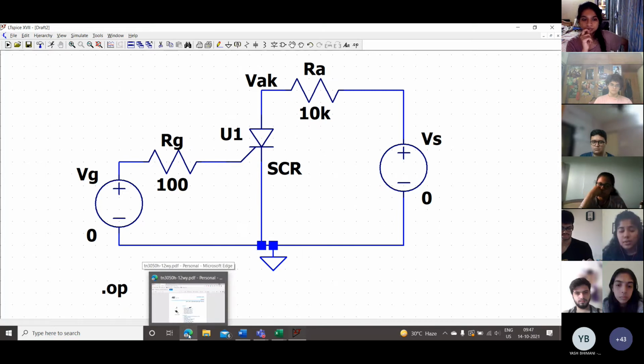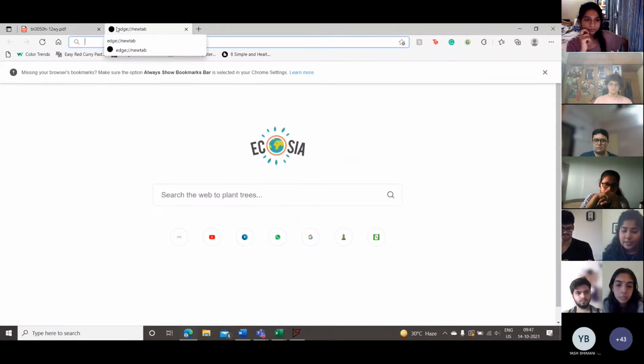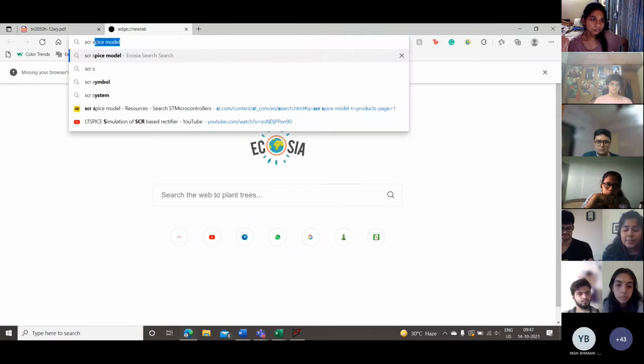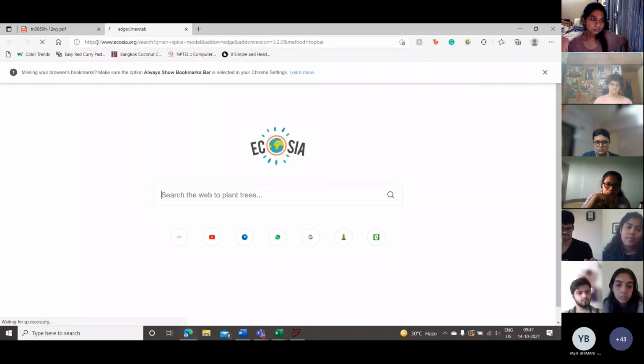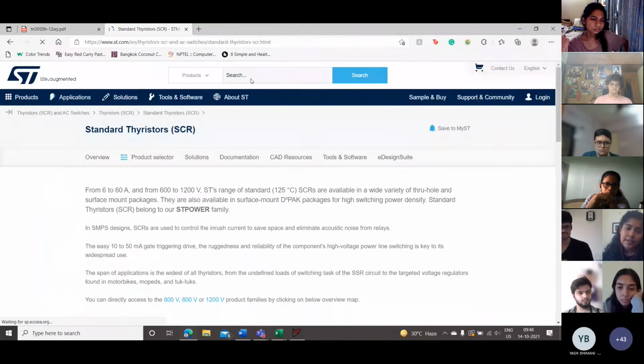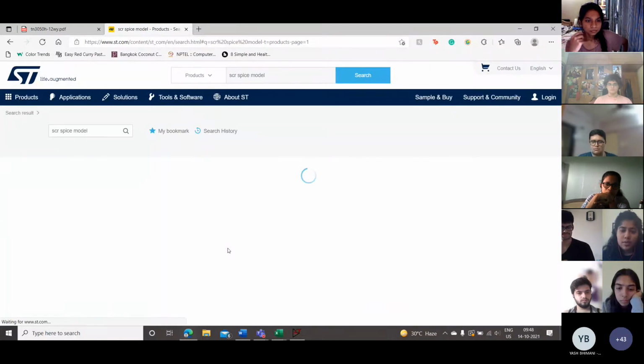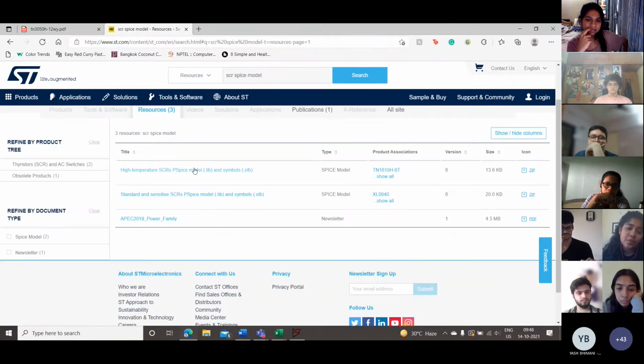So at this point, this is going to be a bit confusing. So let me know if I'm going too fast and then I'll slow it down. So what I'm going to do is just type SCR SPICE model. And I'm going to go to ST, this website, and I'm just going to go ahead and type this. It's giving me 3 different options for SCR here, and you can select any. I'm going to select this high temperature PSpice model.